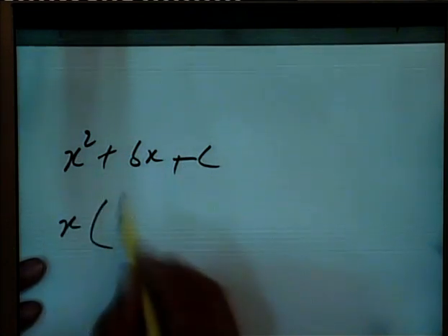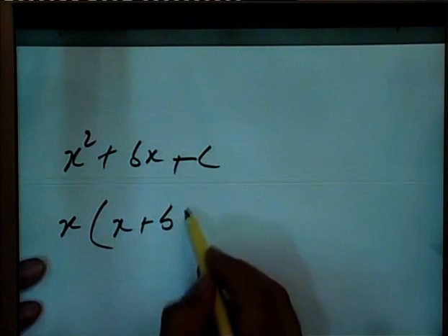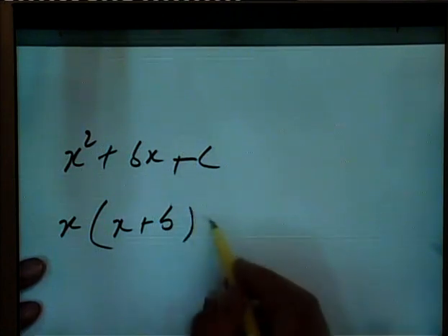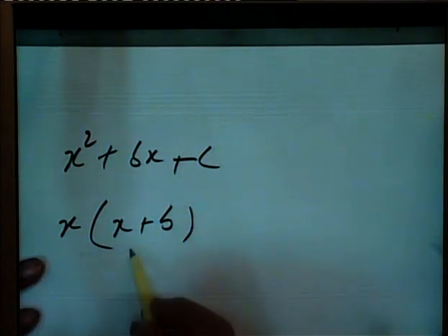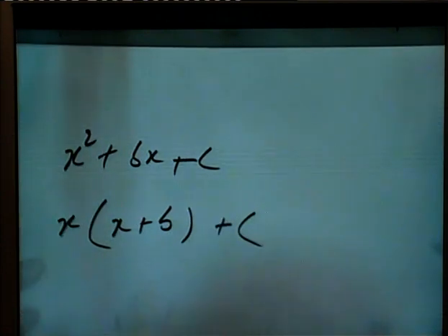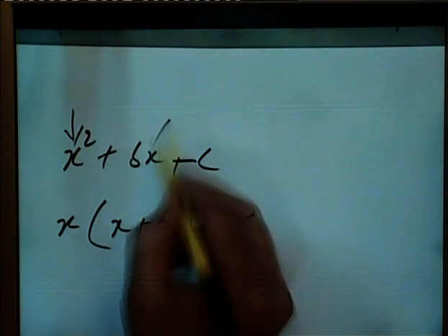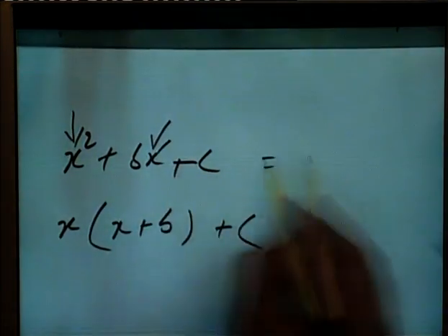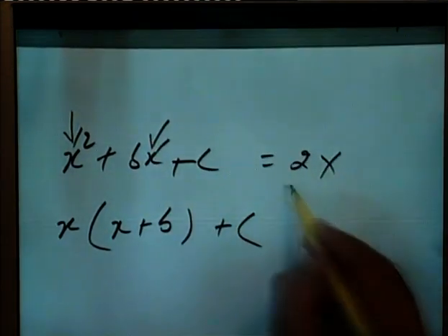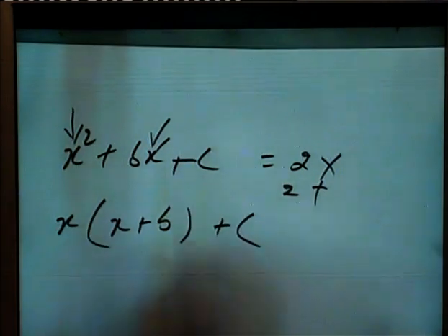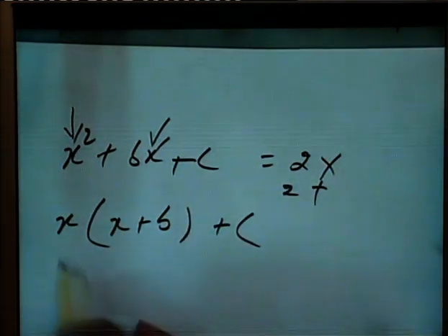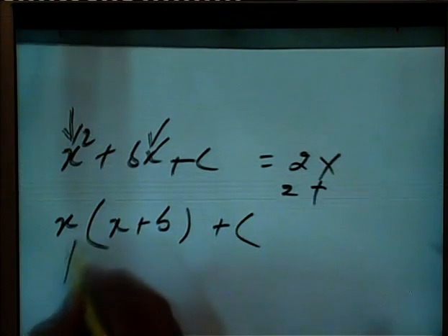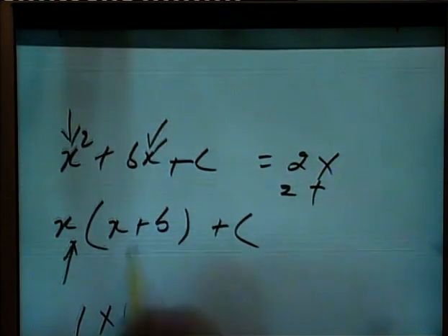If we take x common, it becomes (ax plus b) times x plus c. It is the same function. To implement the original we require 2 multipliers and 2 adders. If we take x common, we require 1 multiplier and 2 adders.